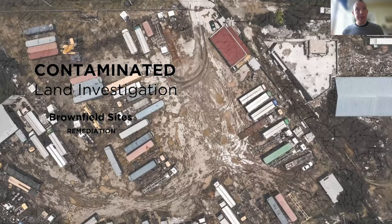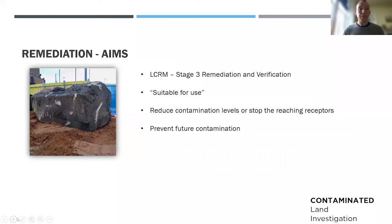So once that phase 3 is complete, specialist contractors can set about remediating the site to make sure it's safe. The remediation work is classed as stage 3 under LCRM. The main aim of the remediation is to leave the site suitable for use in accordance with brownfield policy. This means the aims will vary depending on what the development is, who will be using the site, and what environmental receptors are around the site.